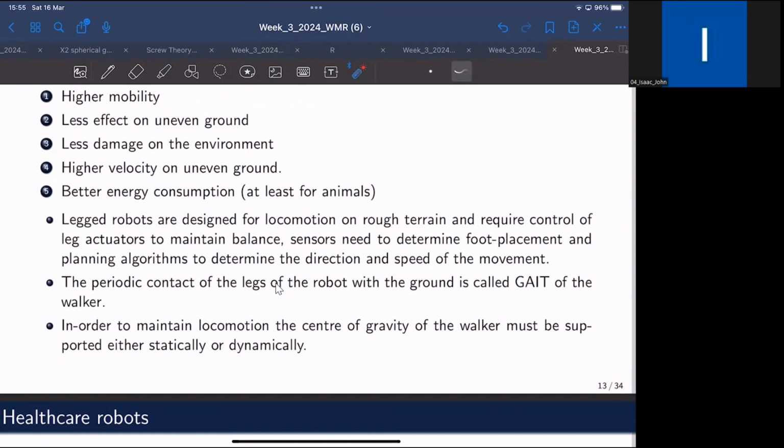If you observe the trotting pace, most of the time their diagonal legs are in phase: front left and rear right would be in phase. And during the other half of the gait, the other diagonal would be in phase. But when they are sprinting, when they are running, they adopt an entirely different gait. The front legs would be in phase and the rear legs would be in phase, apart from the diagonal phase. So the animals have different kinds of gait that they could employ depending on the kind of motion that they are executing.